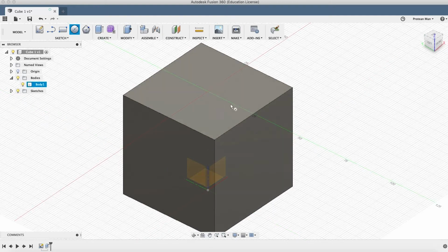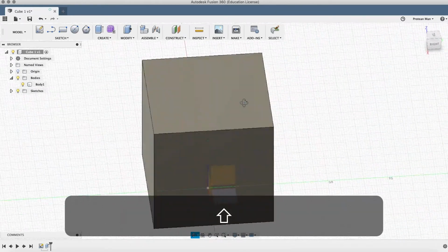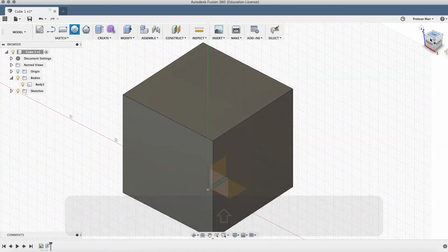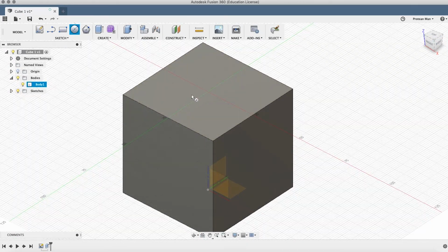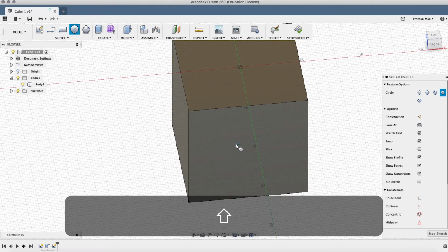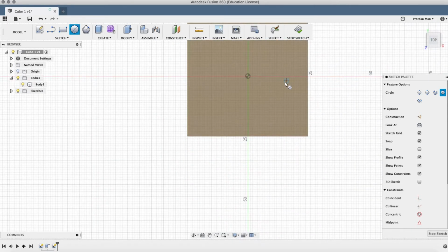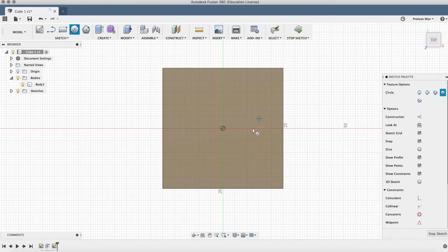Find any of the sides, it doesn't really matter. I'm going to use the top side. I bring this back around to the top, front, and right. So top, now it's going to snap me again to a vertical view. The sketch view always changes to a top-down view. Whether it's the top or the side, it will change to whatever this becomes and make it like you were looking straight down onto it, which is very handy for making sketches and making exact measurements.